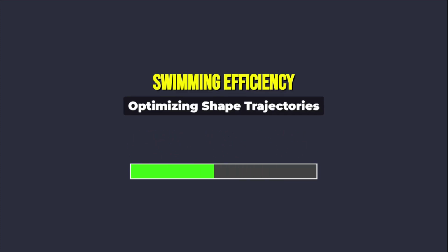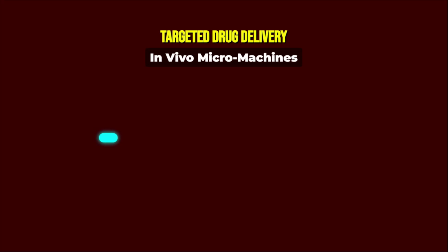The efficiency of a low Reynolds number swimmer is measured by the ratio of the energy expended to the distance traveled, often termed the swimming efficiency. This efficiency is inherently low because energy is continuously dissipated against viscous drag. Optimal gaits are those that maximize the enclosed area in shape space relative to the total path length traveled. Research focuses on optimizing the sequence and magnitude of hinge angle changes to maximize the net displacement per cycle while minimizing the required input power, typically resulting in complex, non-intuitive motion patterns.